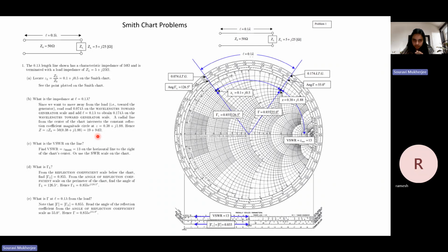So, what we are currently trying to do is solve Smith chart problems, basically trying to calculate and evaluate reactances and impedances using the Smith chart. I hope you have had a basic idea from the course. So I'll just continue with this question. Here, this was our load. We normalized it with the characteristic impedance of the transmission line. So this was the value.